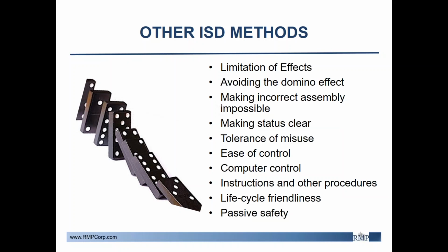Make sure to consider the entire life cycle of a process. Problems and hazards that can arise during construction and demolition can be overlooked, so it's important to focus design not only on normal operations of the plant, but also from the ground up and back down. Lastly, passive mitigation. Passive mitigation doesn't run high risk of mechanical failure or lack of activation. In fact, the whole idea of passive mitigation is that it doesn't need to be activated. So in general, passive mitigation systems should be emphasized over active mitigation systems.